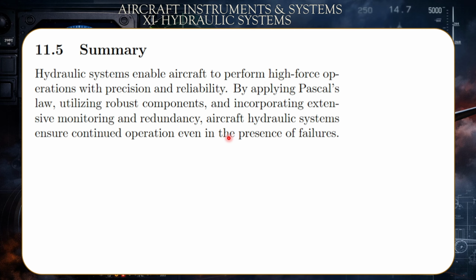Another detail I may have missed is how to detect the quantities in the hydraulic fluid. Now, you have different methods. You can use a mechanical arm that would be pushed by buoyancy. When you have the fluid available at that level, it would move an arm as a floater. That arm, when it floats, would turn and switch an electrical circuit on or off, which in its turn would be detected as the presence or absence of the hydraulic fluid.